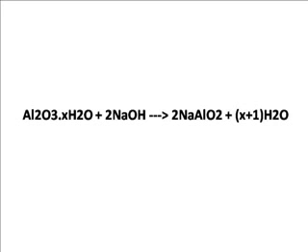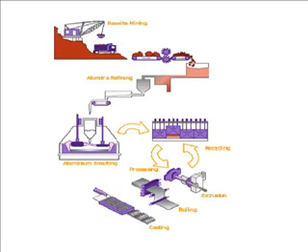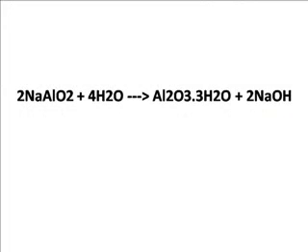After the extraction stage, the liquid, which contains the Al2O3, must be separated from the insoluble bauxite residue and purified as much as possible, and then it is filtered into a decomposer. The red mud is thickened and washed so that the sodium hydroxide can be removed and recycled. The next stage is the decomposition stage.